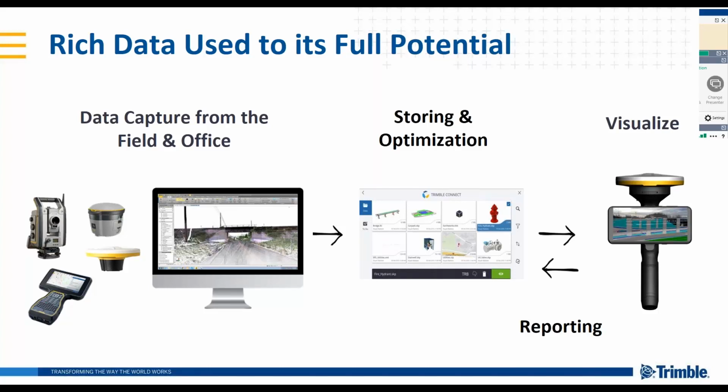And it will then go through a little process where it's processing the data. And when it's ready, you can go out with your SiteVision kit, or you can tell a representative of your crew to simply start up, and it will then visualize it. So we're using Trimble Connect as the holding place for the data, and when we visualize the data through SiteVision, it visualizes the data from our Trimble Connect side. And of course, that also goes the other way. So any data you either collect or any to-dos you create can then be reported back the same way as it came from.